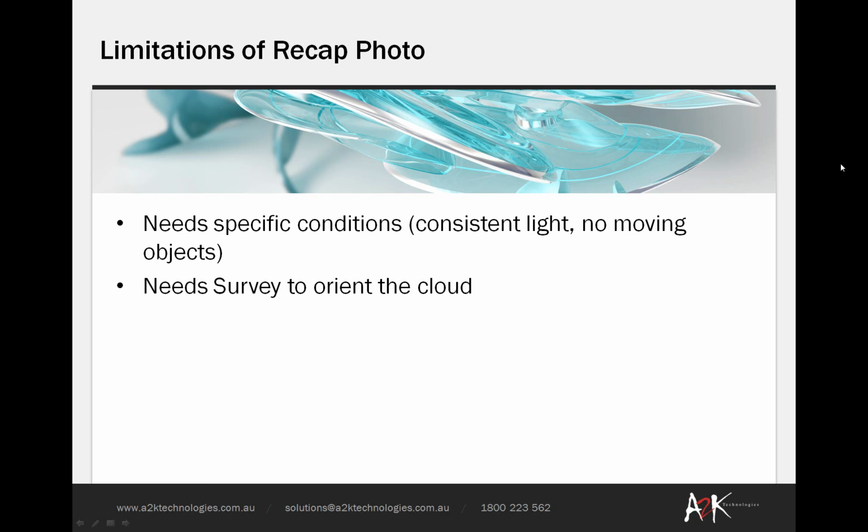So the limitations really are that you must be careful with your conditions. If there are too many moving objects, you really don't expect it to work that well, and you want the light conditions to be consistent. You also need to be careful with the photographs and make sure everything's in focus with a narrow aperture. Then the other thing is that you really do need an old-fashioned survey as well to orientate your point cloud into known coordinates.